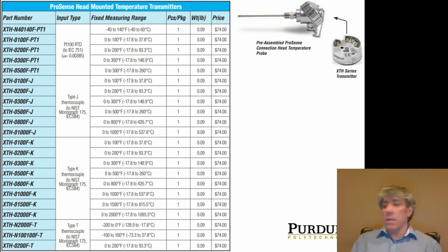What it means is, let's say you've got a 12-bit input card, so 4,096 different levels. Well, it means you got 100 degrees divided by 4,096, which is about 0.024. So you could measure a temperature change at the thermocouple junction of about 0.024 degrees Fahrenheit.